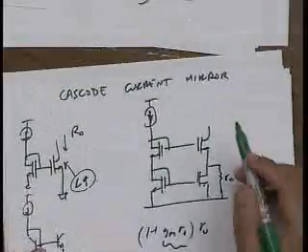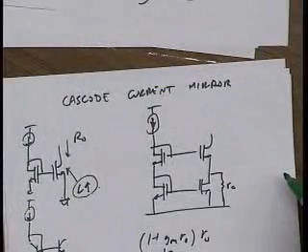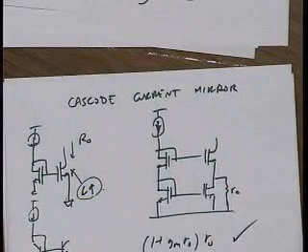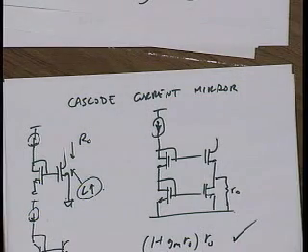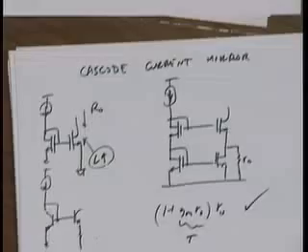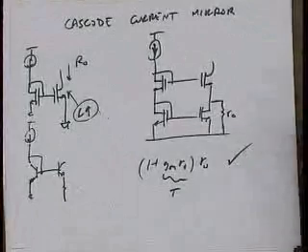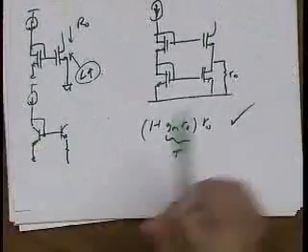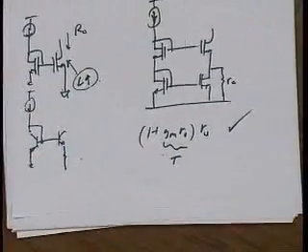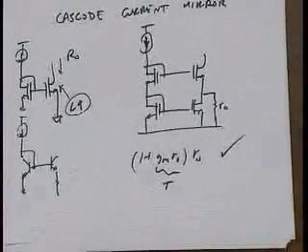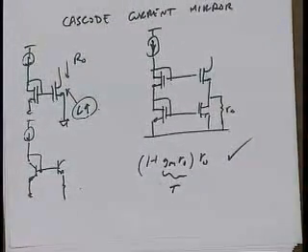All right. What's a disadvantage of the cascode? First of all, it looks like we have a huge benefit. GMRO is 20, 30, so I get a huge increase in output resistance. What's the price to be paid? Headroom? Yeah. Swing, again. It's always about swing.